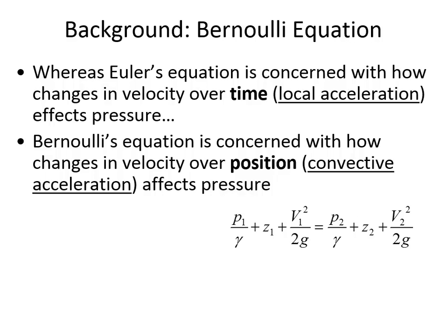Sometimes we'll be smart about it and we'll find some location where the pressure is 0 and we'll make life easier for ourselves. But other times we'll actually be using Bernoulli's equation to find some unknown pressure, so we don't always cancel out the pressure head term, because sometimes that's the objective of applying Bernoulli's equation: to find an unknown pressure and how it changed.